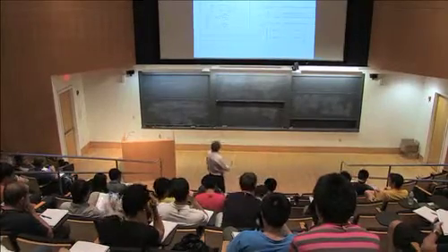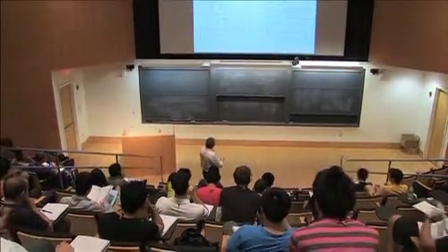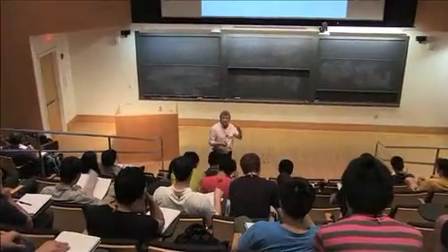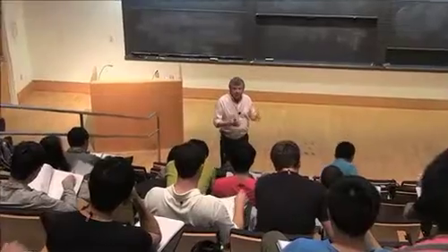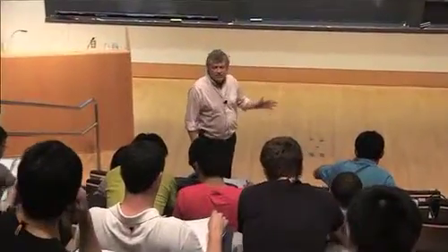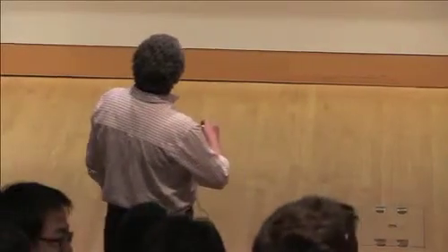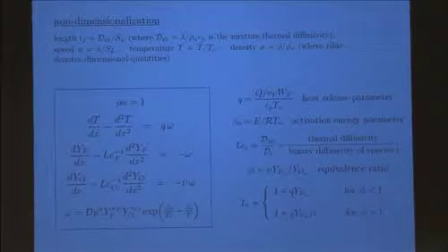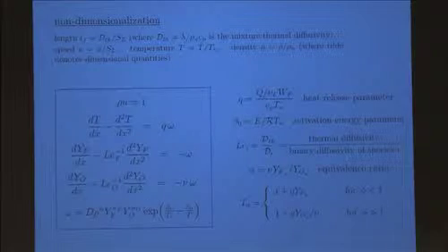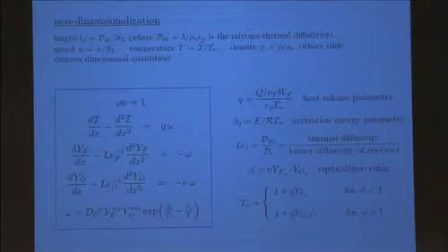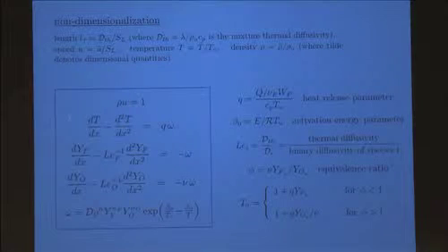We stopped around here yesterday where we wanted to address the simplest problem probably in combustion of premixed reactants. And this is a planar flame steadily propagating into the fresh mixture. And so the governing equations that were put in non-dimensional form are framed in this box. We discuss all the parameters, including the expression for the Damköhler number D. And essentially what we are faced with is solving this nonlinear problem.